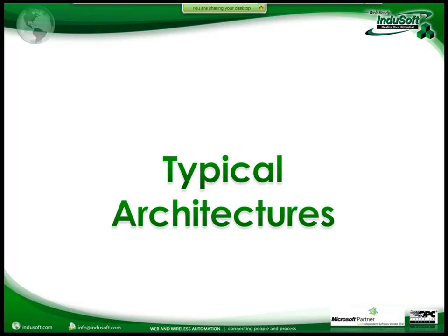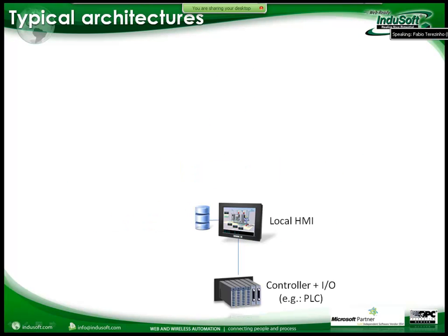Having said that, just getting started on the typical architecture. This is the most simple architecture possible. You would have one device running in the InduSoft Web Studio, talking to the devices, remote IOs, controllers, even a PLC if necessary, but pretty much reading data from the meters, from the sensors, and providing this data to the user, typically with a local database to store history information, so you can visualize how the variables changed, the trend of variables over time.